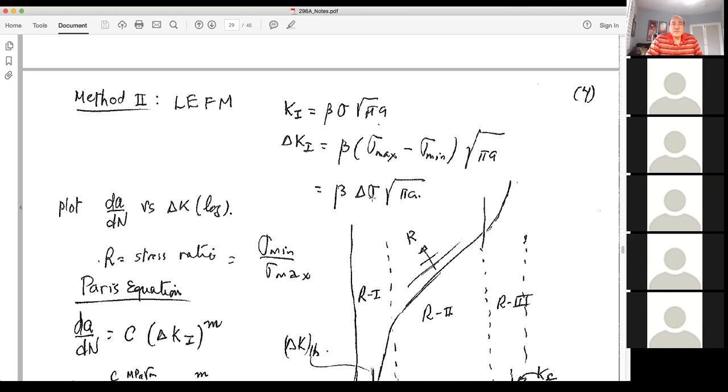So in this case, if we know a fluctuating stress, as in our project and the connecting rod project, we would know it at a critical location. We have to choose a critical location for the crack at the fillet or at the contact area between the connecting rod and the shaft, or in the middle of the connecting rod.